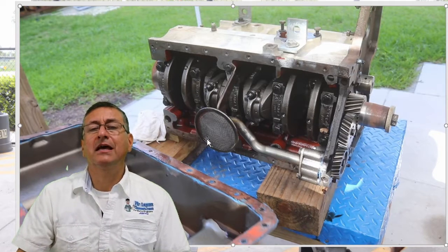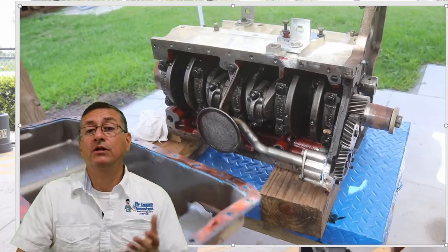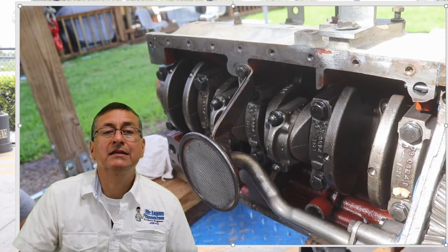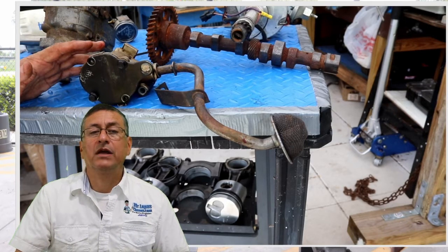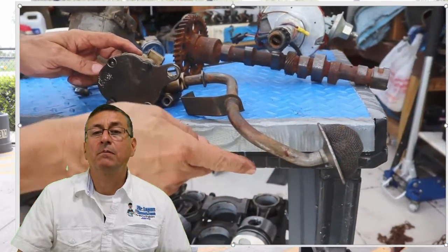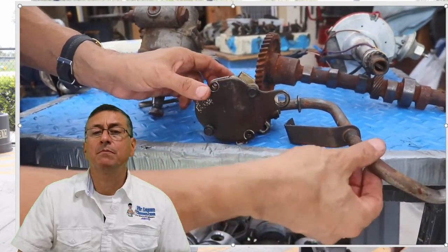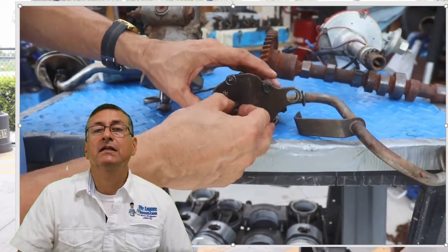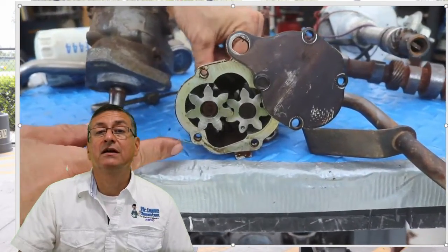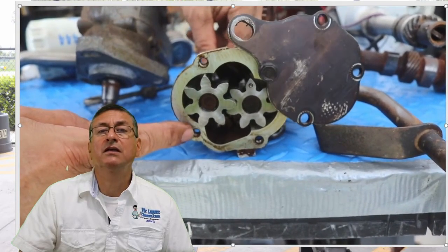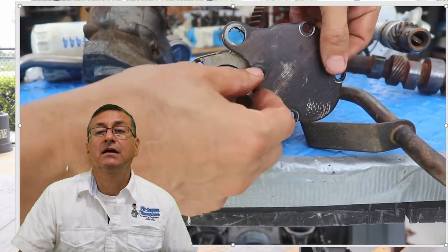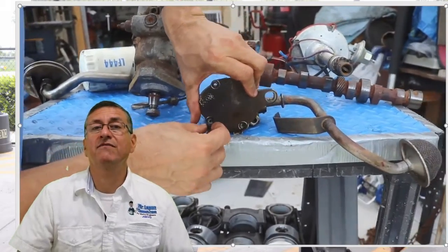Okay, this is the oil pump, and now we are going to try to explain how the oil pump works. This is the explanation about the oil pump. Okay, my friends, this is the oil pump. Correct. This is the strainer. The oil is suctioned over there and enters the pump. The pump internally has two gears. This is the driver gear on the shaft, and the other one with the dot is the driven gear. Correct. On the other side, the shaft of the driver gear.